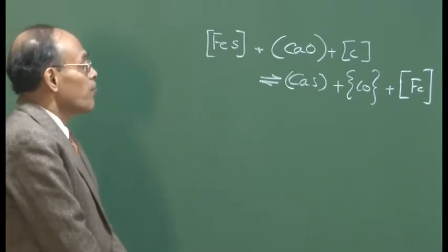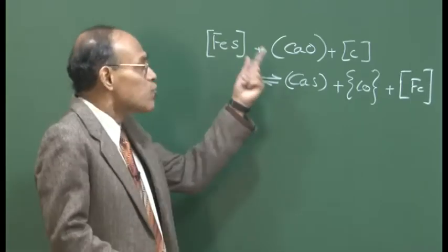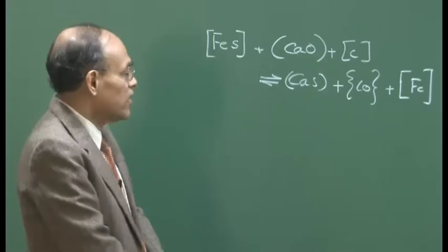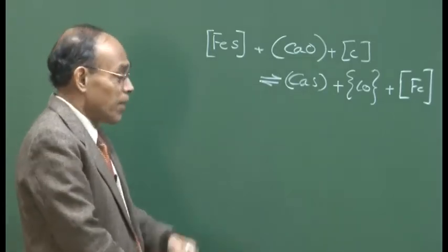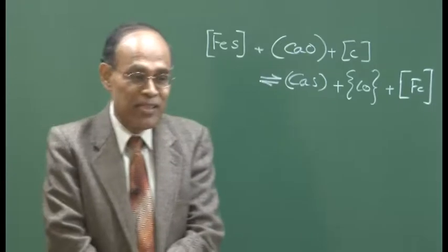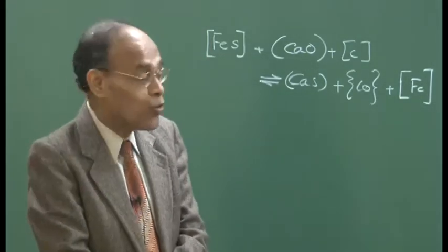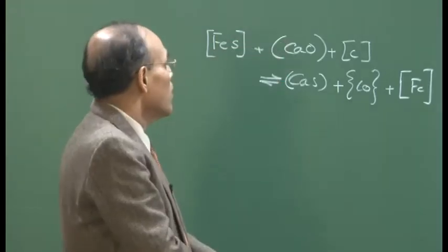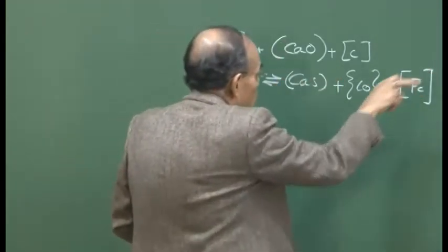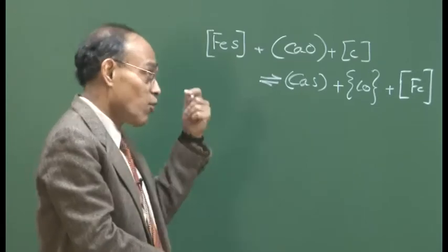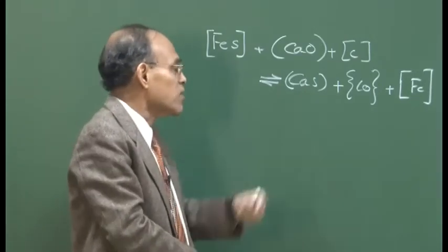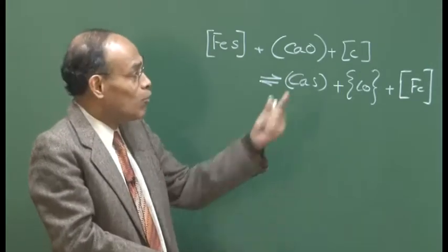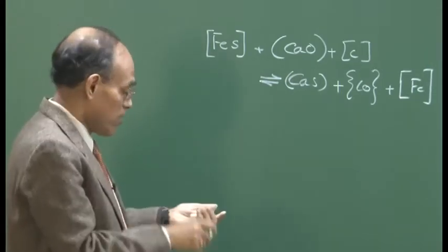But we see this is a weakly exothermic reaction. So, I would say that desulphurization should be favored at relatively low temperature, but I have also made the statement that when you increase temperature we always note that more sulfur gets transferred to the slag phase. That means this reaction is favored. I also mentioned in my last lecture that this is precisely because of the kinetic factors, and that will come out now when I talk about the kinetics of the desulphurization reaction.